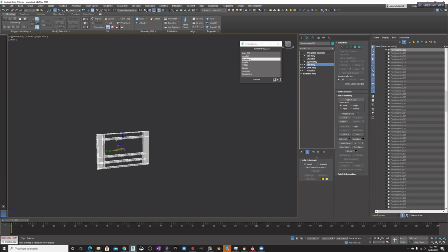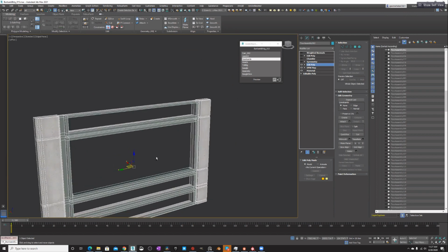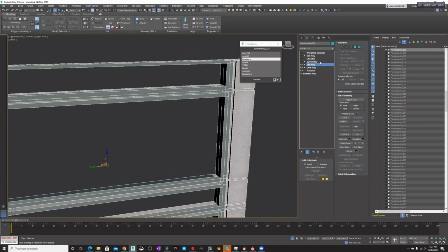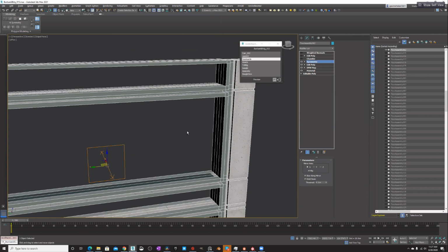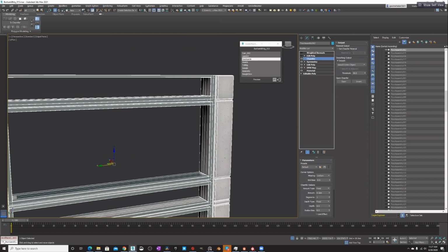Then this is just part of the modeling process, so there is one with no window. Then I'm doing a symmetry modifier, adding a chamfer. One thing I didn't want to do was put a chamfer on the glass, right? If you put a chamfer modifier on the actual panes of glass, the normals go a bit weird, so you don't want that.